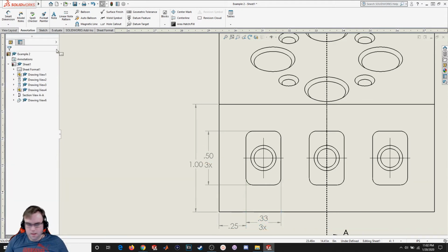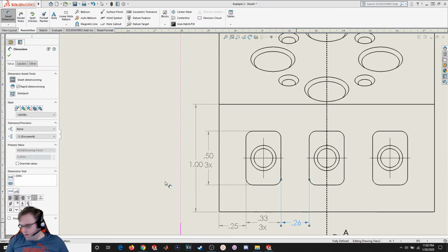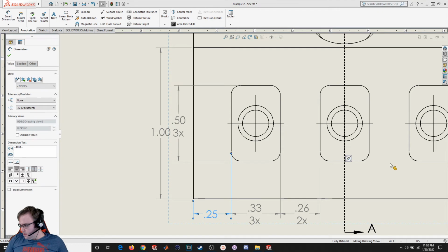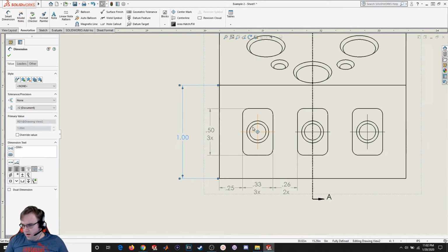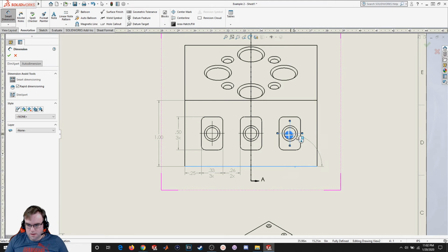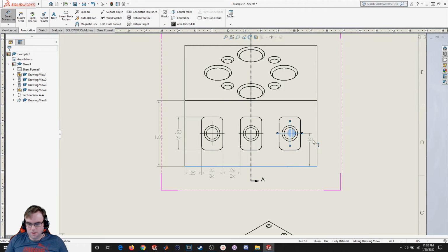Okay. I've got here to here. And I'll put a note, should be 2 times, so let's put 2x. Alright, I'm just going to drag this up, put it in line, and I think that that's good. Drag this over for neatness sakes, and now I've got here to here. Oops, nope, not an angle. Here to here, not an angle. Vertical dimension, here to here. There we go.